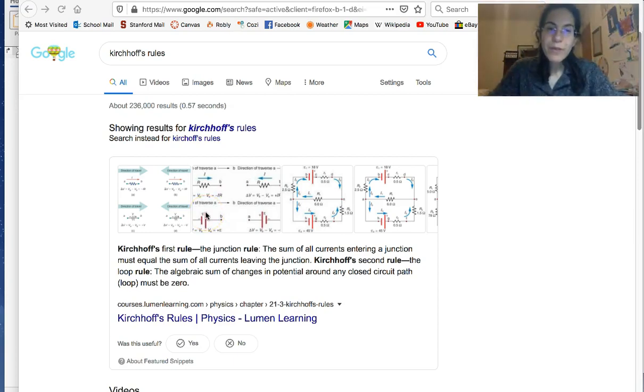Now in a circuit with only one AC source or only one battery pack, this is intuitively obvious to even the most casual observer. Kirchhoff's second rule comes into its own when you have interesting systems and networks with multiple voltage sources, and you simply do the conservation of energy going round and round, where everything you hit, this battery here, and IR for this resistor, and IR for that resistor, and whoa, that battery is facing the wrong way, and oh wait, IR for that resistor over here is going to equal 0.